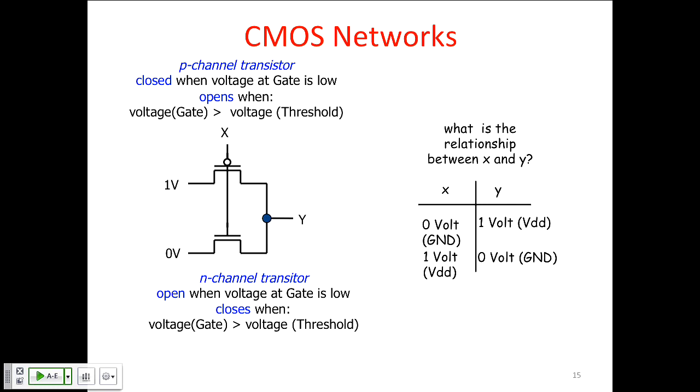A NOT circuit, right? So this inverts a bit. You have a bit that comes in as a 1 or a 0. It leaves as a 0 or a 1. We've inverted it. So this is a very primitive logic function. This is an inverter, right? And that's how you build it. Just 2 transistors connected this way, and you've built a logic gate.